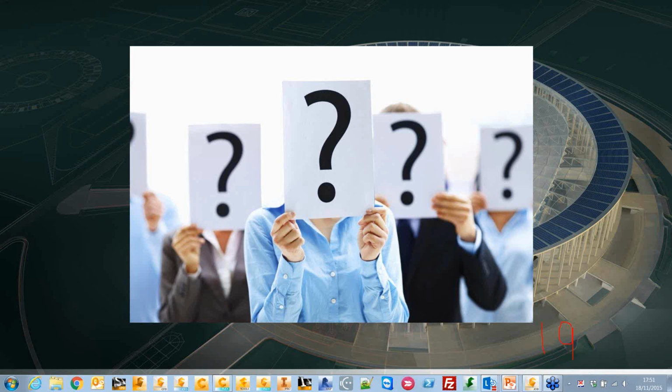Okay, we've got a few minutes left, and there's quite a lot of questions. A variable temperature on the wall. Apparently, there was a problem with that in the past. I don't think there is now, as long as the part that the temperature is assigned to is suppressed and it's not an internal surface again, then that should be totally fine.